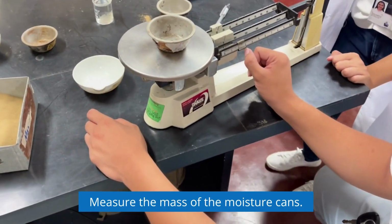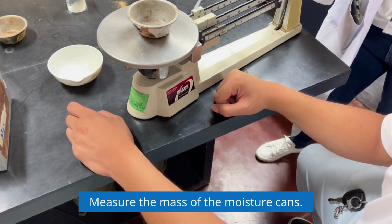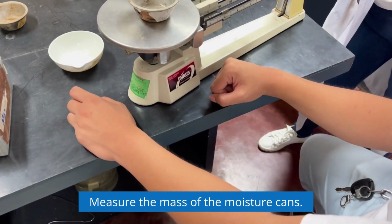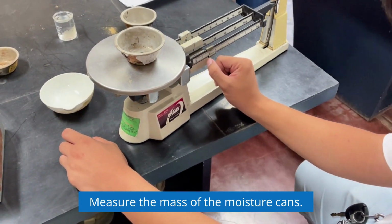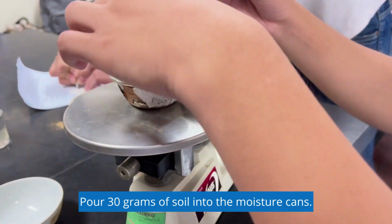We measured the mass of the 3 moisture cans and labeled them. For trials 1, 2, and 3, the mass of the moisture cans are 0.0123 kilograms, 0.0117 kilograms, and 0.0123 kilograms respectively. We then put exactly 30 grams of soil in the moisture cans.